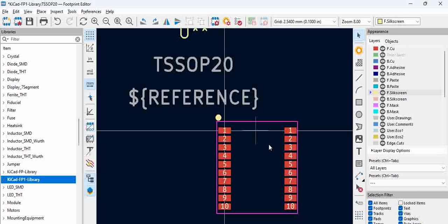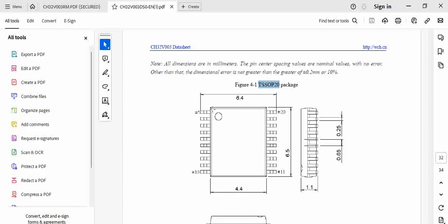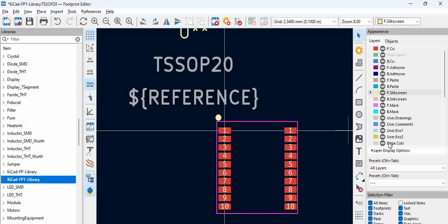And then one more thing what we have to do is we have the component, right? So we have a courtyard that is defined, but we need to know approximately where the component sits. So to enable that, go to the component, and what we can do again here is this is again a silk screen part, so we can draw a line here.